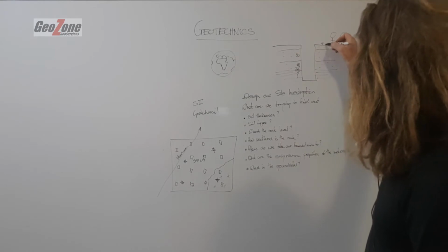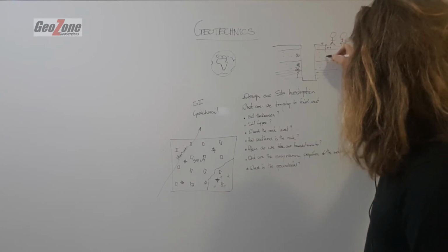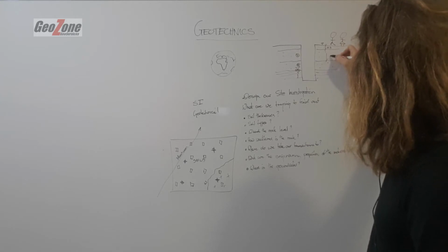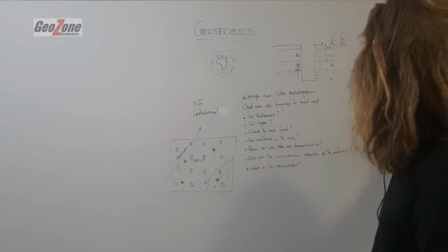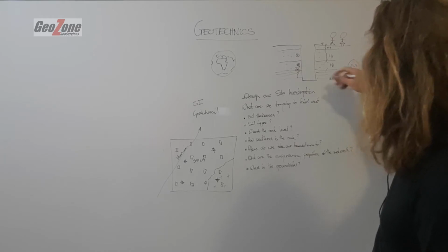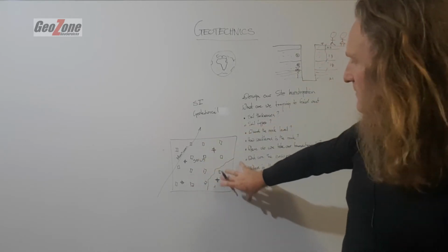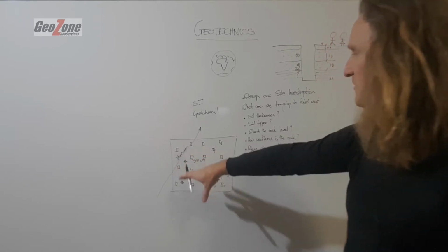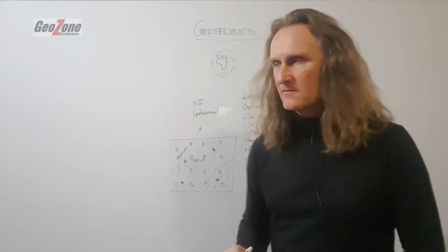Soil thicknesses, so we can measure that. Well, that's 0.3 for the colluvium, and let's say it's 1.3, 1.8, 2.1 is refusal. Now we understand. We're starting to get a picture of what's going on. We dig test pits across the site. We find the rock is closer to the surface here. We find it gets down into deep, wet alluvium down there. We start building a geotechnical model. We understand what's going on.